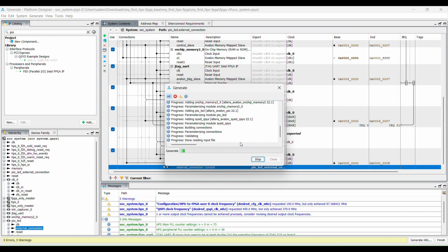And this is the main part that we need to connect the HPS to the FPGA. Without using this tool, we will not be able to communicate the design, the FPGA, with the ARM processor. So right now I'll be done with the FPGA part. Then I will go and implement the software part, and this is what we call co-design, when we use the hardware and software together to implement a system. So I'm just gonna wait for it.